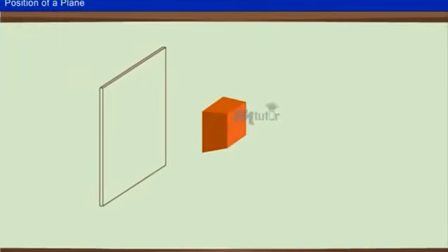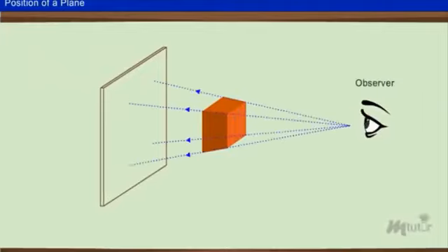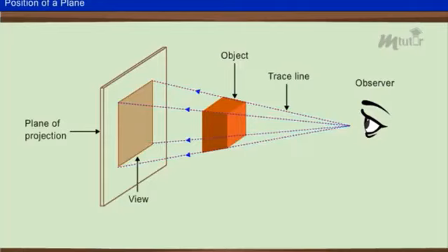Before heading into the traces of plane surfaces, we will see what a trace is. Any of the plane surfaces, extended if necessary, will meet the reference planes in lines unless it is parallel to any one of them. These lines are called traces of the plane surfaces. The traces of plane surfaces have been categorized into 4 types.